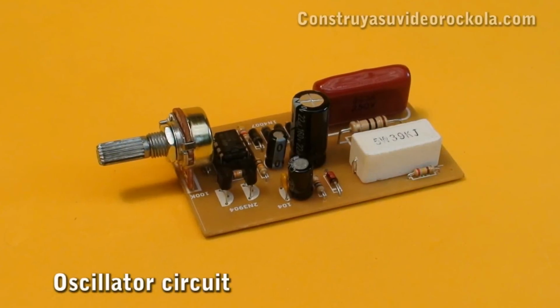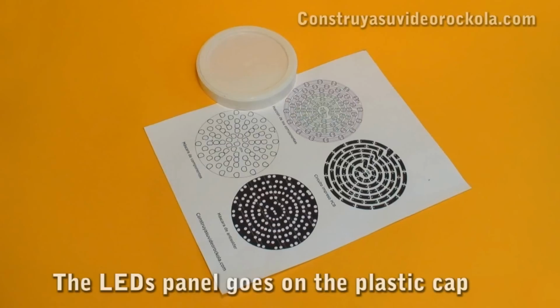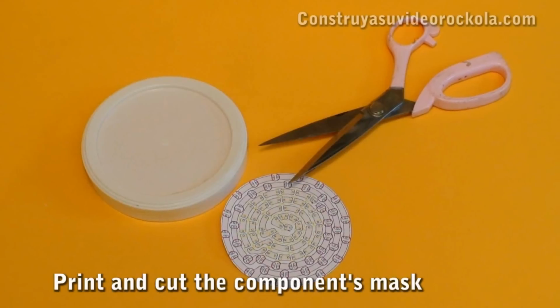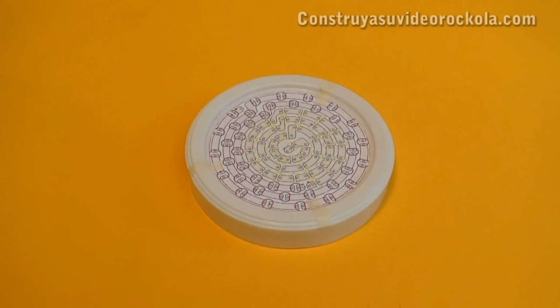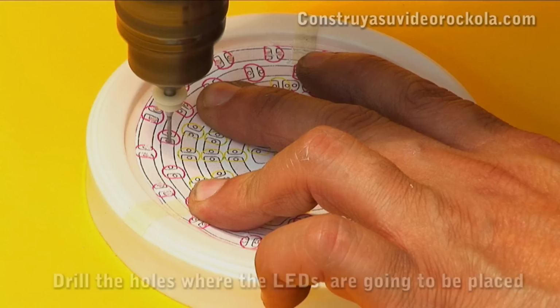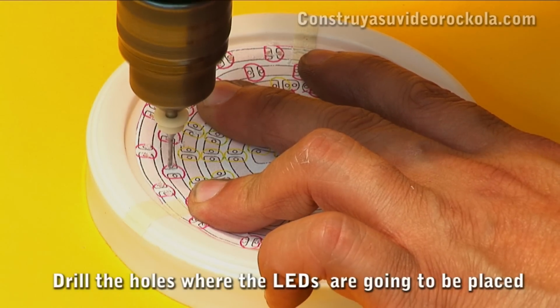Having built the oscillator circuit, we must make the panel of 80 LEDs. We will use the lid of an ice cream jar. The mask with the component layout found in the PDF file is printed and then cut with scissors. Paste the mask pattern on the cap and, with the help of a drill, drill all the holes where the LEDs will go later.